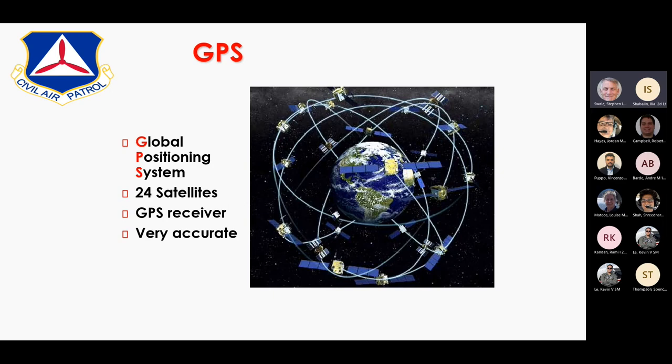Cross-track error. I find cross-track error to be an excellent tool. It's an excellent tool in the G1000, and it's even more valuable when you're flying one of the retrofitted GPS boxes. A cross-track error is something that can be displayed in a similar fashion on the smaller 400 and 600 version Garmin boxes. This can be applicable for parallel searches where you want to stay on a particular line that you're flying. It can be very valuable if you're flying a point-based search.